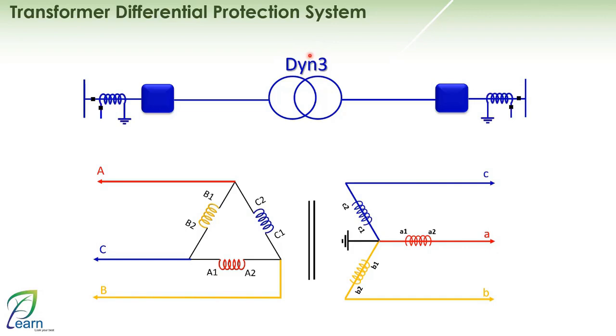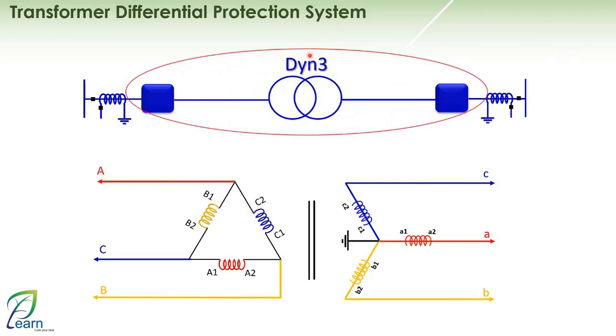Of course, if we refer back to the lectures on protection systems, and I will show you my link now, we will know that my protected zone is formed from where the CTs are placed. Therefore, all this red area is my protected zone. Naturally, there is a difference between the term protected zone and protected object. The protected zone can contain more than one object. As we can see, for example, I have here a part of the GIS, a circuit breaker, a cable, and a transformer. On the other side, I also have a cable, a breaker, and a part of the GIS or switchgear, depending on the case. Therefore, there can be more than one protected object within my protected zone.